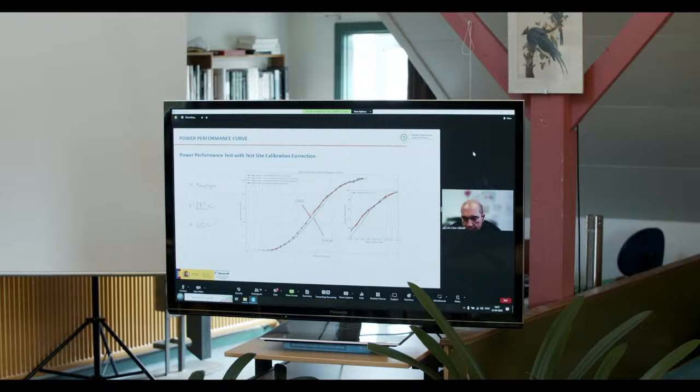More or less, we see that the SCADA power performance is significantly less than the performance that can be obtained with the real wind speed that the LIDAR could see in the position. So this is a question of yaw misalignments, supposing the operation of the wind turbine, but the difference is significant.